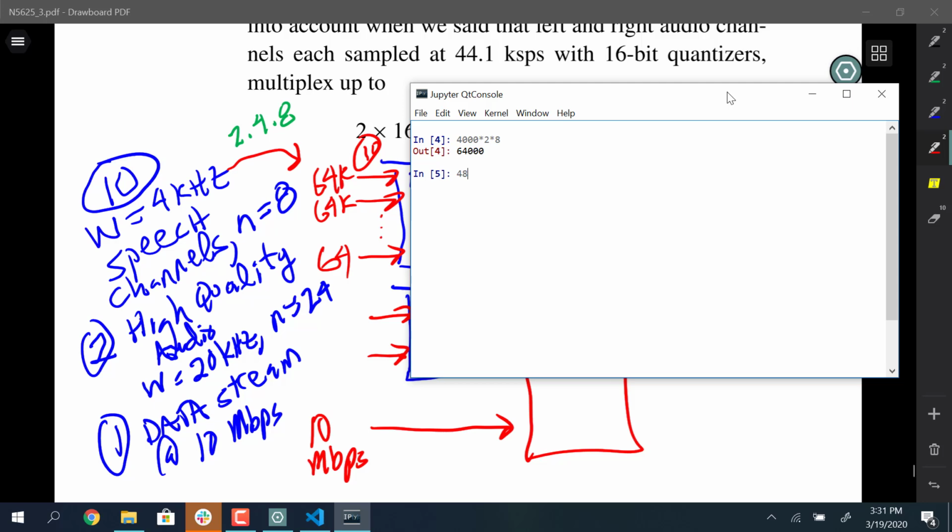They'll oversample it even higher for higher fidelity and fewer issues due to filtering. So even though we're starting at 48, I'm just going to run some numbers here. Let's say 48K, which is to handle the bandwidth W. And then we have 24 bits per sample. That's 1152 kilobits per second.